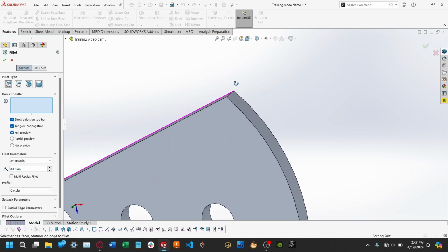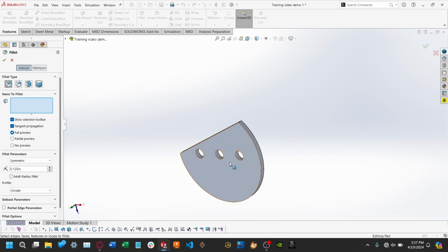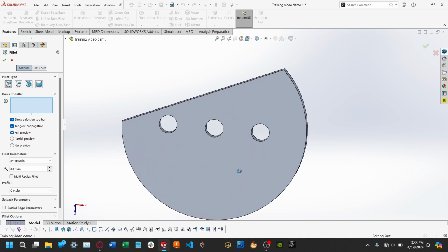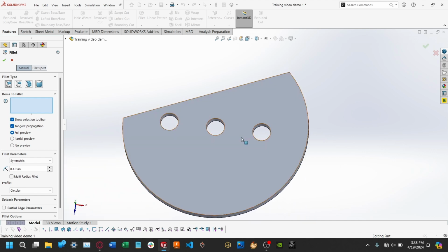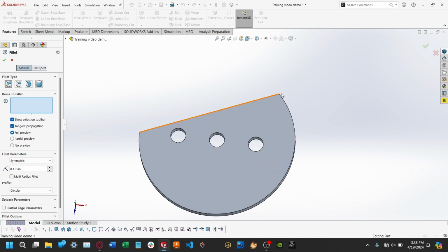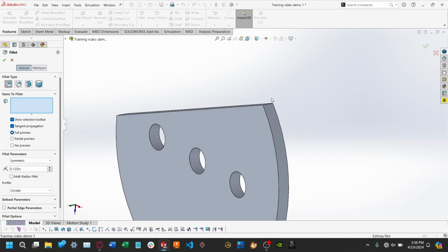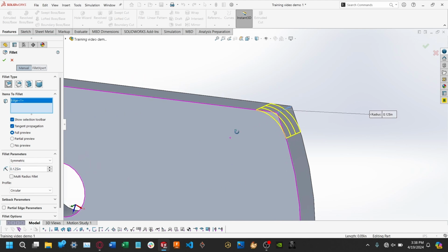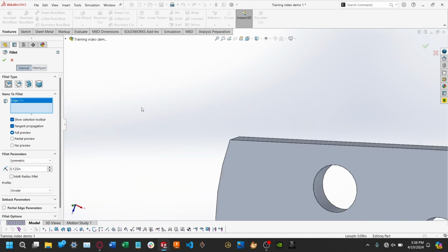These are features that either A, do in fact require three dimensions to function, or B, features that can only exist on an already extruded part. I don't count cut extrudes in this, because cut extrudes just basically use sketches, and you can build cut extrudes into the sketch of an extrude by putting a contour inside of another contour. However, you don't want contours to intersect like a Venn diagram. That creates selected contours, which is not something fun.